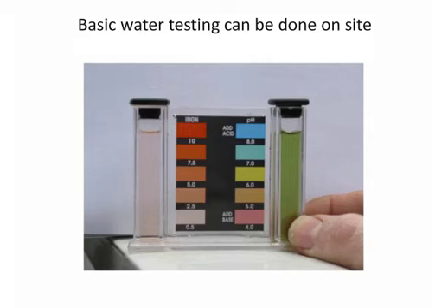I own a basic water test kit. That's mine right there, and I did test to see what levels of iron, because again, it's going to affect what kind of heat exchanger I'm going to choose to use, as well as the recommended maintenance levels. And that's not the only test, guys. pH and iron, I always check for total dissolved solids, which is the particulate. I do a number of tests in the field, but that's just the beginning for me.